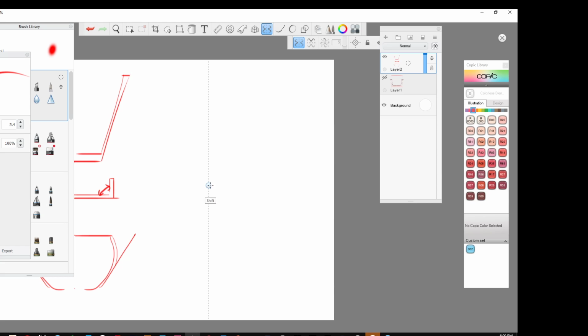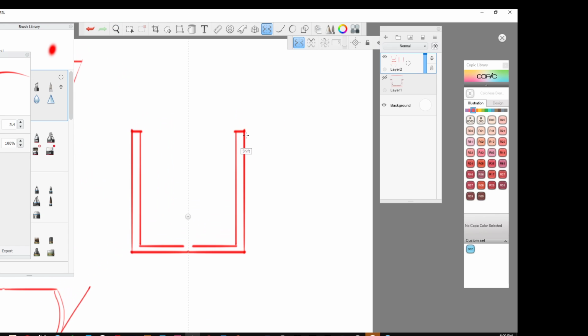And sometimes what happens is that last little part up in here where the tool's coming off, right in this area here, since that's the last little piece, there's usually what's called a little flashing. And what flashing is, as the plastic is poured in, you'll sometimes get this little bit of edge of plastic that seeps out. What happens is this part then all of a sudden gets scrapes and you notice it.